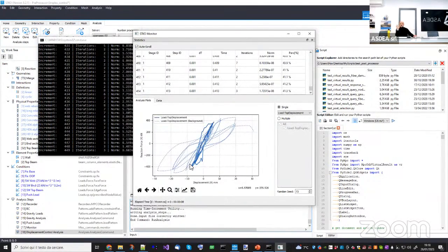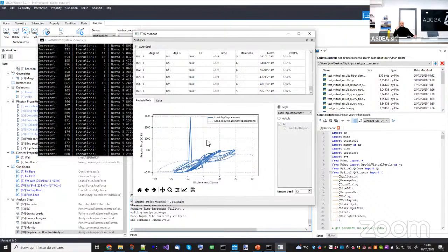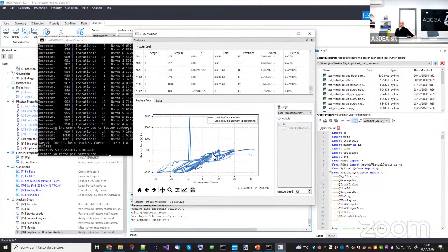Now, this is not so large a time step, probably it's fine, you see here. But if I decrease it even more, you see here some instabilities, which were not visible in the other model. So if you see something like this, you will probably realize that the time step is too large. Actually, it took only 30 seconds to finish this analysis.